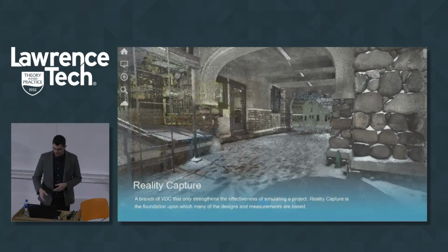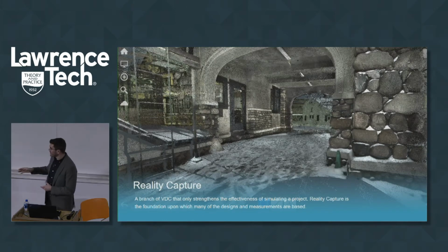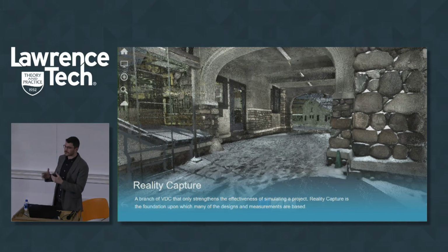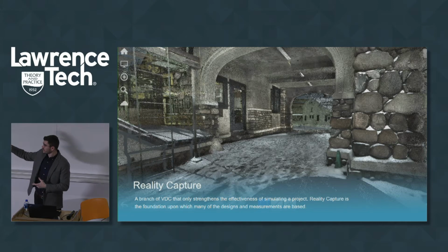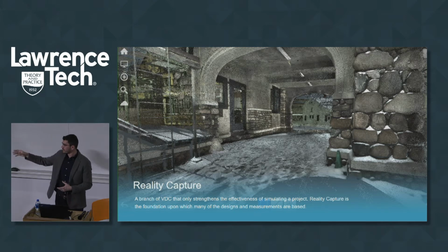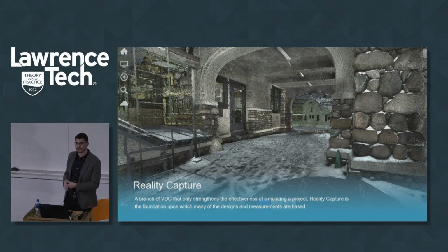it. So this next image, some people who aren't familiar may think it's just a photo, but it's actually what's called a point cloud, which is a series of millions of points that together create a three-dimensional environment that is measured off of, extracted off of, and this can then have incredible amounts of detail with the scale of this, just the reality capture industry itself. I think it's a really great image because it shows just the detail in the rocks that you're seeing. You're seeing the deviations in the archways there. You're seeing snow in between the joints between each rock. You're even seeing footprints, and you're actually getting a little bit of logistical information there to know how many people use this footpath here or here.